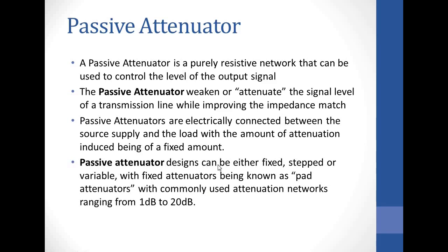Passive attenuators design can be either fixed, stepped, or variable. We are going to consider fixed attenuators mainly, but for variable attenuators, basically what we are saying is that you can tune a knob, more like your volume, the way you increase or decrease your volume. You can also increase or decrease your attenuation. That's with variable attenuators.